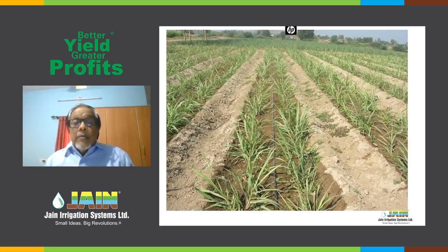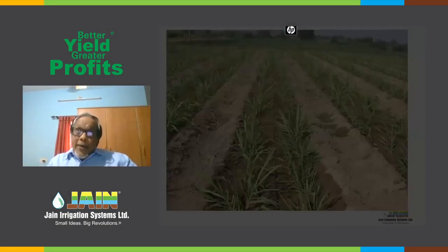And here, compared to the previous system, the cost will be far less and the soil is not loaded with plastic. But I agree, that was a sandy soil. This is a loam, probably a clay loam type of soil, with more clay in that. I understand that actually. But I'm trying to give you the difference. That is why I said even in the first figure, this closeness is not required for lateral.